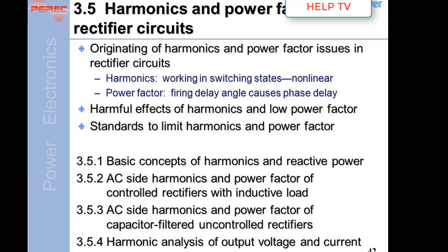3.5 Harmonics and power factor of rectifier circuits. Origin of harmonics and power factor issues in rectifier circuits. Harmonics: working in switching states, nonlinear. Power factor: firing delay angle causes phase delay. Harmful effects of harmonics and low power factor. Standards to limit harmonics and power factor.